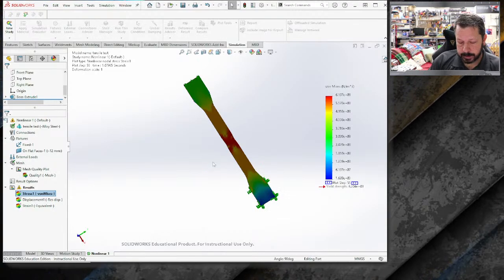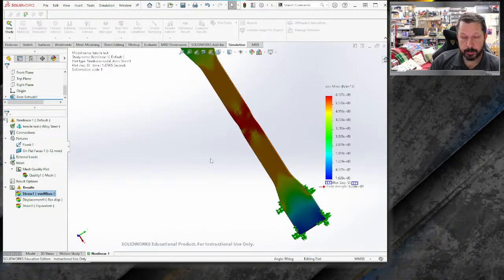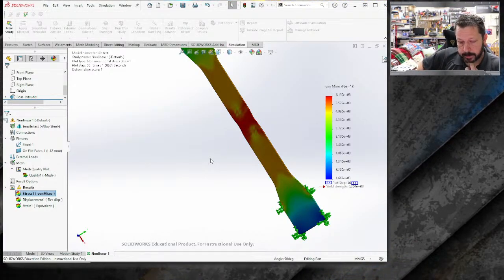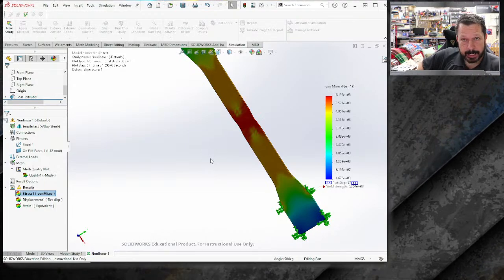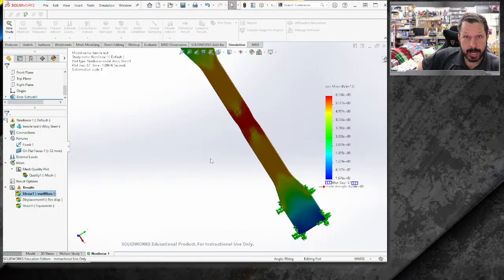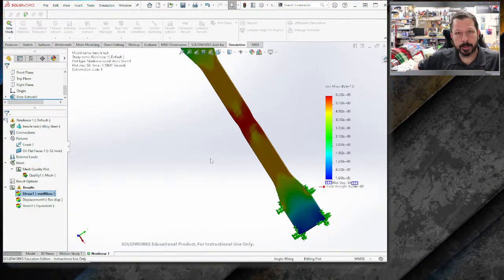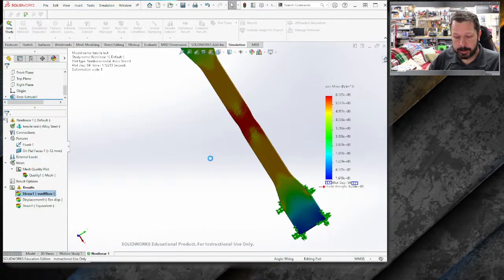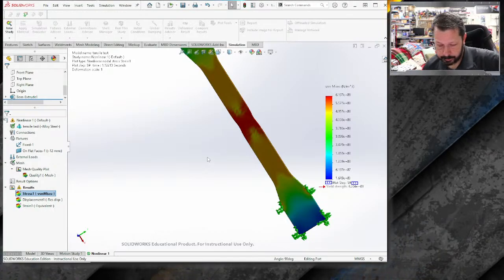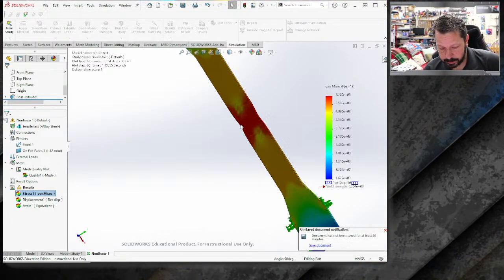Now you can really start to see the stress is developing highest here where that neck is formed because it has a smaller area. The axial stress that would be measured in this, which is called a tensile test, is from an axial force pulling this part of metal apart, and the area is smallest there, and so the stress is highest there. Force over area is how you calculate that axial stress.